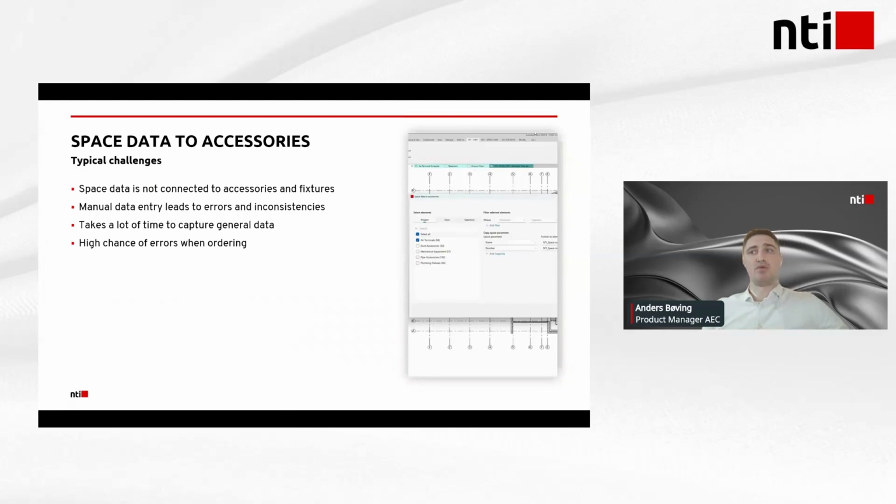I know that you can maybe move a location point and so on to utilize Revit's built-in functionality, but in many scenarios, maybe you have sockets placed on the concrete above the ceiling, or you can have convectors in the ground, in the floor, and so on. So components that are not actually placed within the space boundaries. So where Revit's default functionality isn't enough.